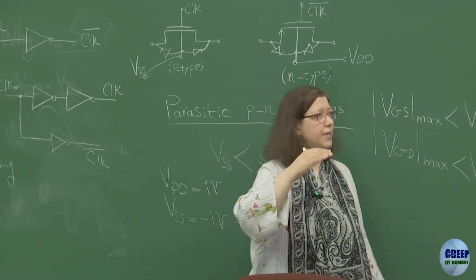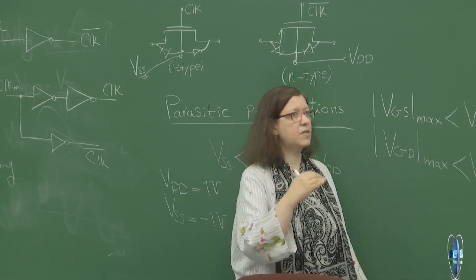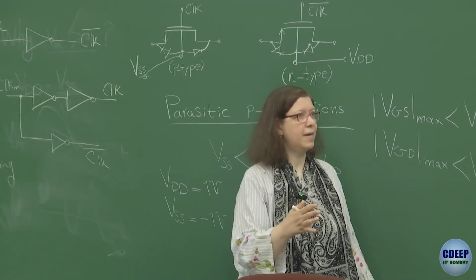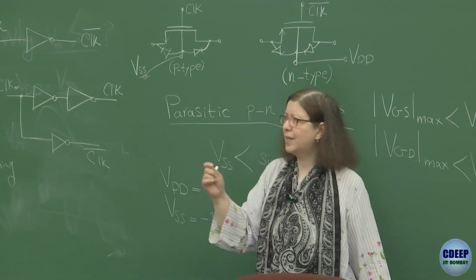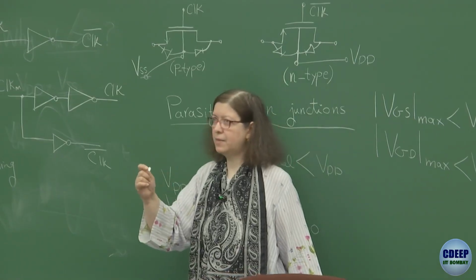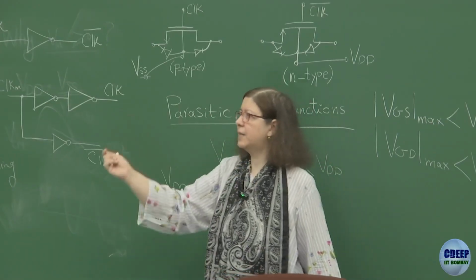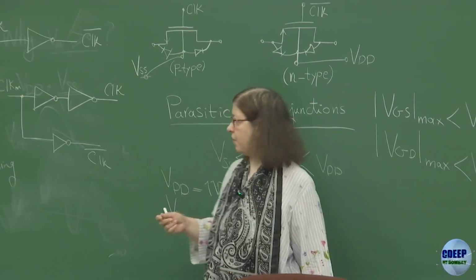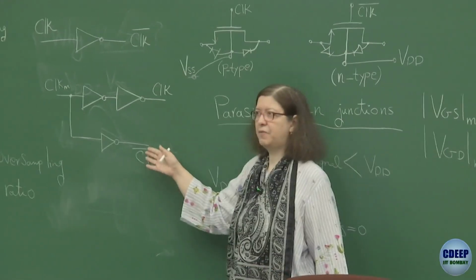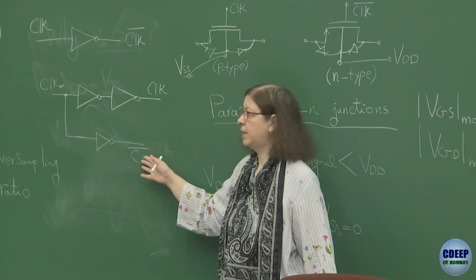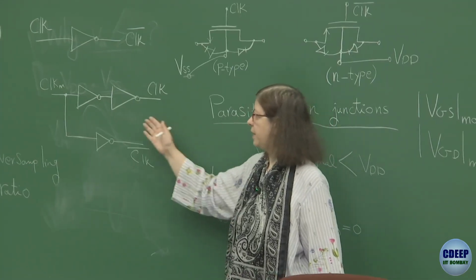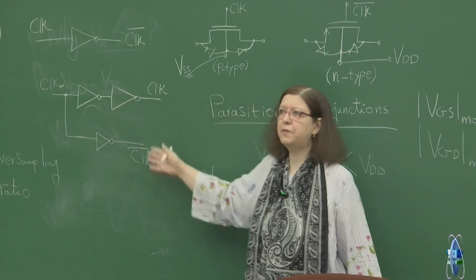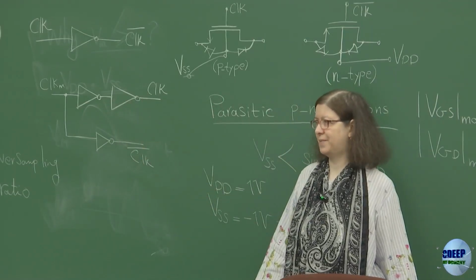When oxide, for example silicon oxide, is grown or formed in any manner, how can you ensure that the devices on the left side of the wafer and the right side of the wafer will have exactly the same thickness? So if you make this solution for one side of the wafer, for the other side, these two don't match. Again, you will end up with a difference between the delay of the two parts.